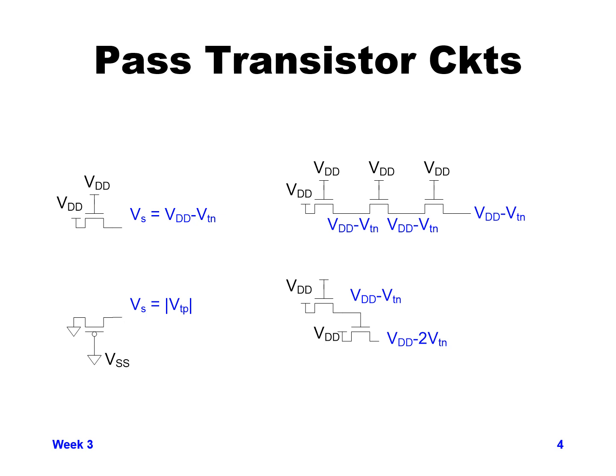So you can see it gets really dangerous if you're using an NMOS only as a transmission gate, using the output of that to go to a gate of another device, especially another transmission gate. So it's not something we typically want to do, to cascade pass transistors with other pass transistors as a general rule.